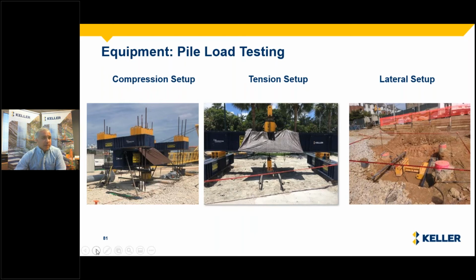That is typical for most North American markets, where you have to run a load test for every project you install. In some areas of Europe and Australia, if you have local experience and you're signing and sealing, you may be able to design and just install the piles based on theoretical analysis, not necessarily running a load test.